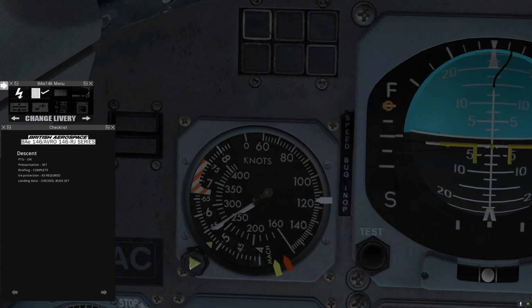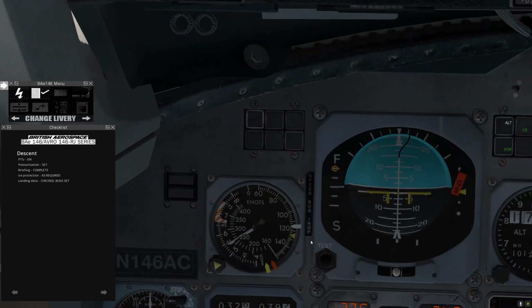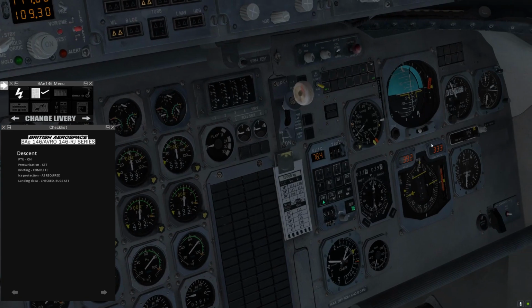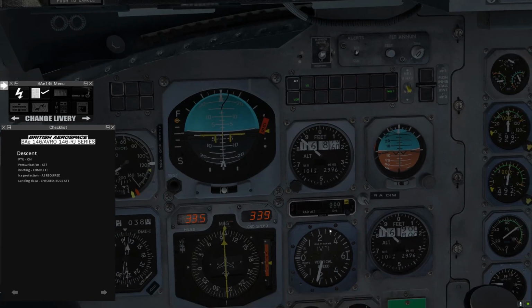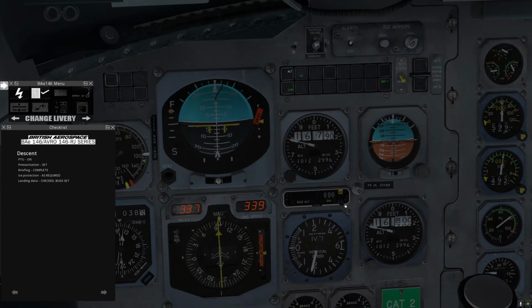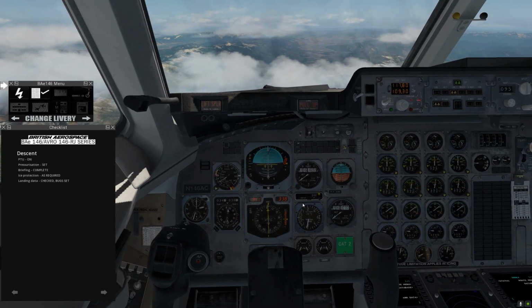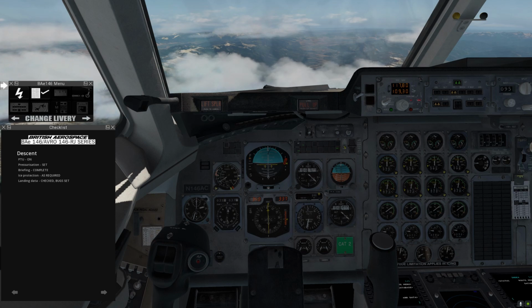And then we're going to use our airspeed bug here for V approach, which is VREF plus 10, or in other words, 125. Additionally, we'll set the local altimeter setting to 29.906, which is already there, and that came from the ATIS. And we would also set our decision height at this time. In this case, though, it's a little bit weird because Missoula's decision height is 1,900 feet. It's an unusually high approach, so we won't set it there. So we'll skip ahead to the next set of approaches as we start intercepting the localizer there.